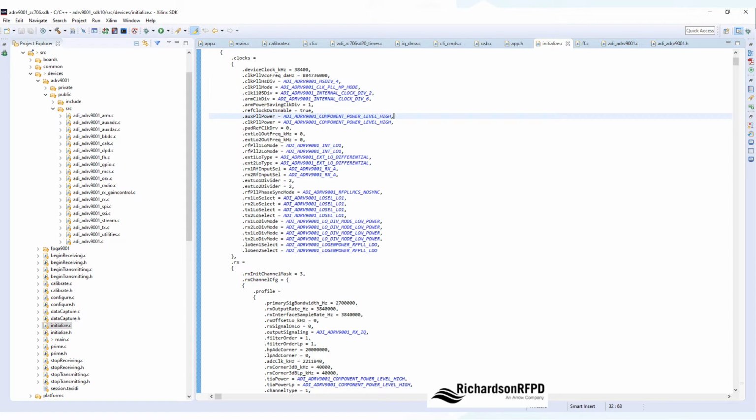The baseband processor Cortex-A9 is used to configure the ADRV9002, process USB packets, and manage the DMA for IQ samples. The software used to configure and control the ADRV9002 is generated from TESS and used without modification. As IQ samples are streamed to memory, the processor ensures they are routed to the USB controller.